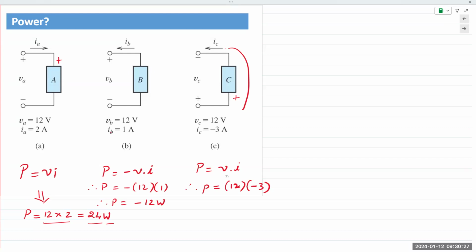Okay. It does not make your analysis incorrect. It does not render your answer incorrect. It simply means that the current is flowing in the opposite direction of what is shown. So do not get bogged down in the direction of the current and the polarity of the voltage. Again, I repeat, it doesn't matter what you assume at the beginning of the problem. As long as your method and your calculations are correct, at the end of your analysis, you will end up with the right answer.